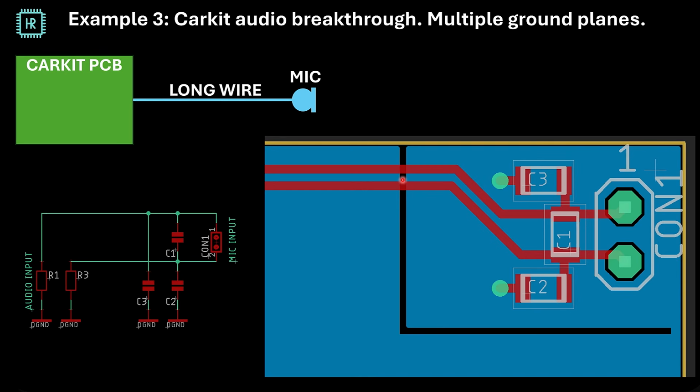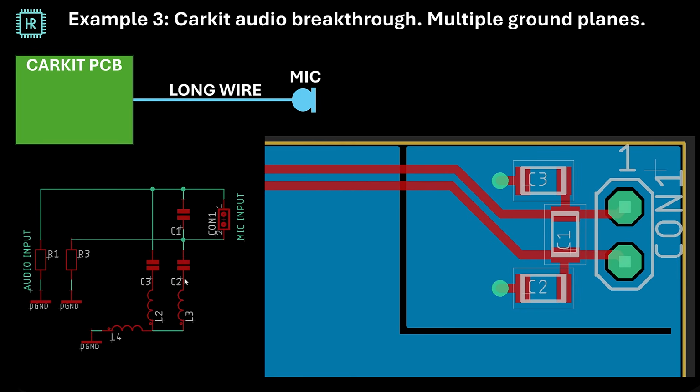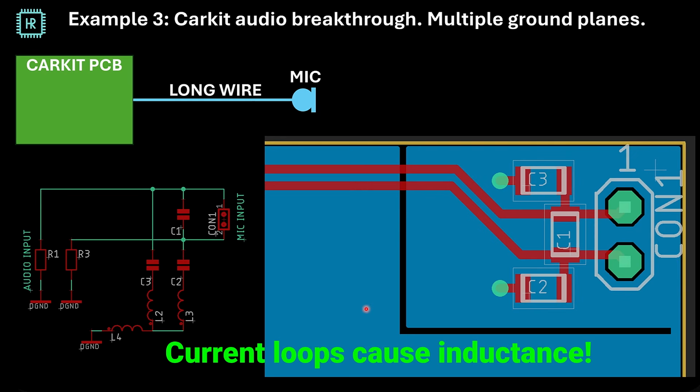And this is actually exactly the wrong way of thinking about it, because what you've actually made here is the following. These 2 capacitors were connected to ground, but in order for the ground return current to go from this place where the audio ground is to the ground of where these wires come in via these capacitors, actually the return current will have to take a detour.